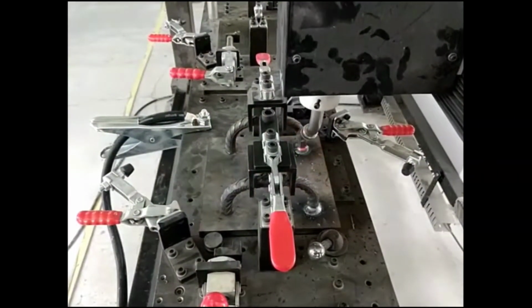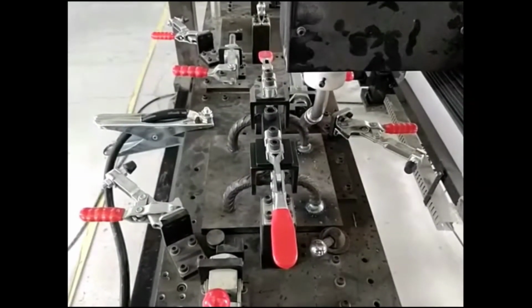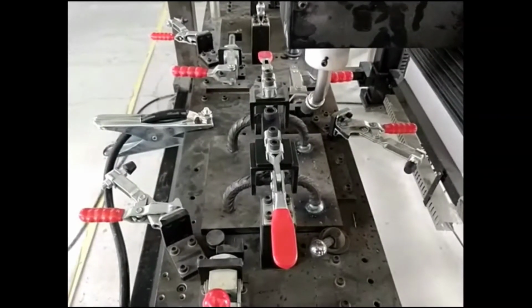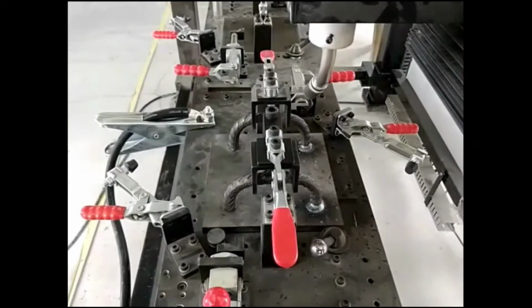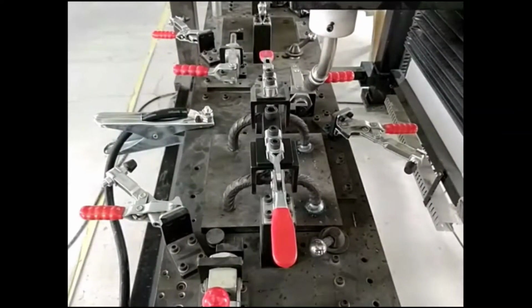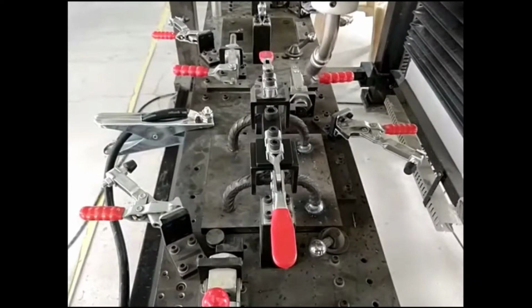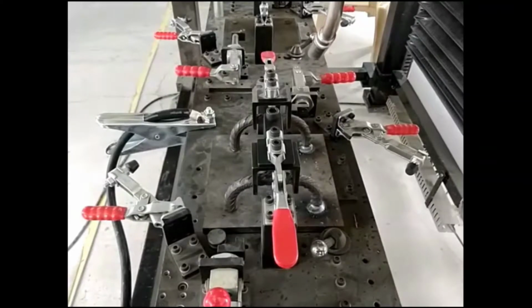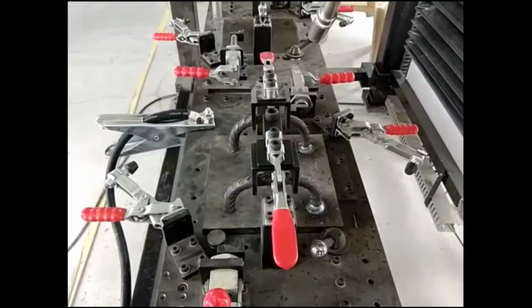We've finished both ends of the TMT bars and we're moving on to the other ends. The kind of finish that you get and the amount of bead that has been deposited is between 8 to 10, which is the required bead width. The base plate we have used here is about 16 thickness. The TMT bar diameter is again about 16 to 20.